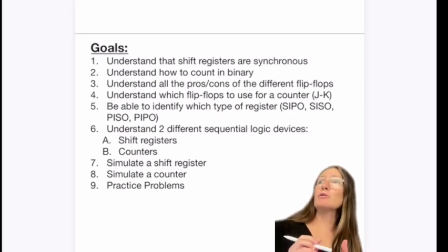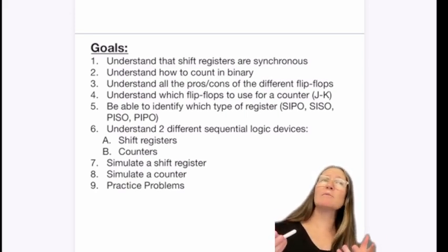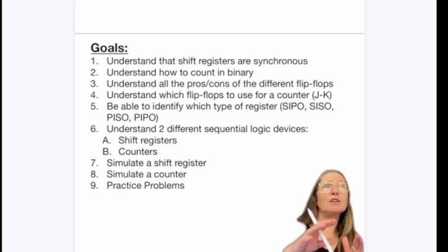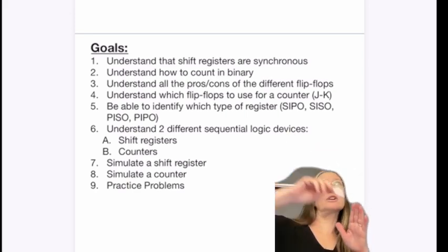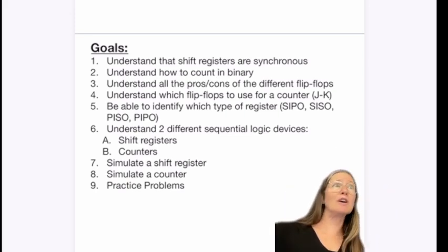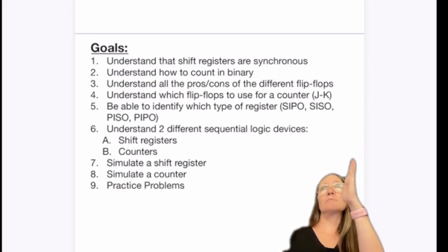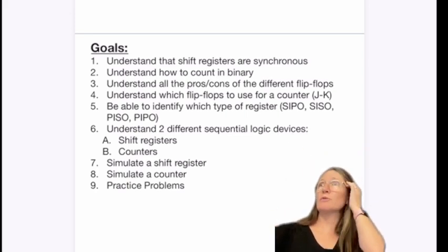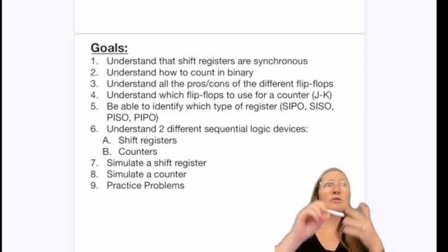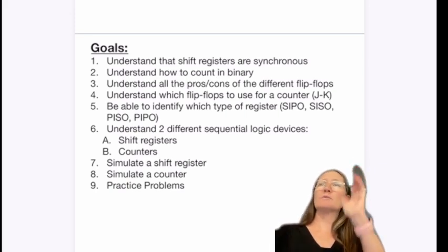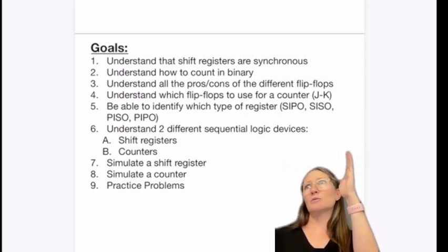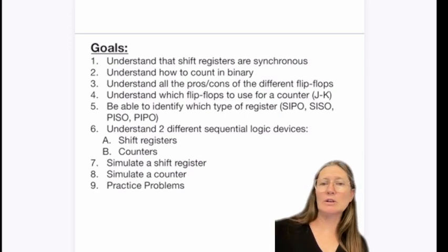Last time we also looked at the clock and how to create a clock from the 555 timer chip. We also looked at how the 555 timer can create what's called a one-shot trigger, and it will create a pulse length depending on the capacitor value. So it would be a specific length of time. So the 555 timer is used either as a clock, or to create a time period with a very specific time on it. It would give you a high until that time has ended, then it would go low. So it's great to keep track of time.